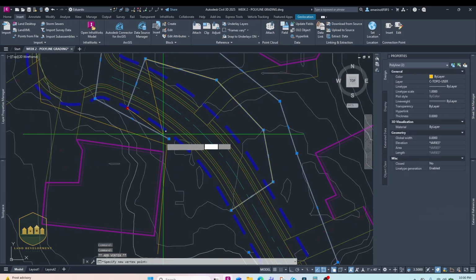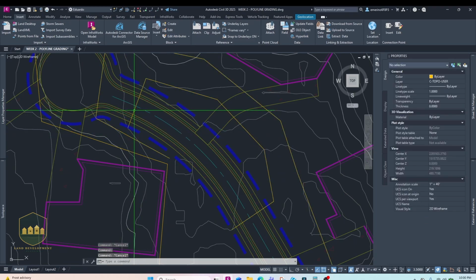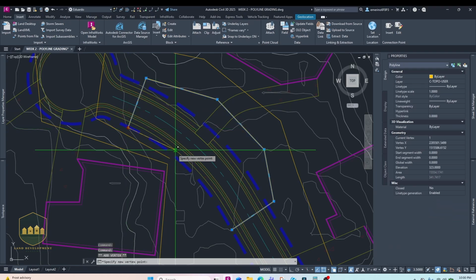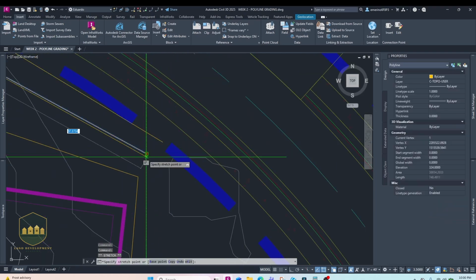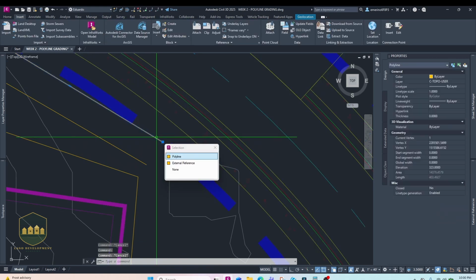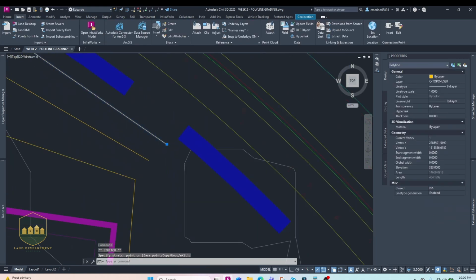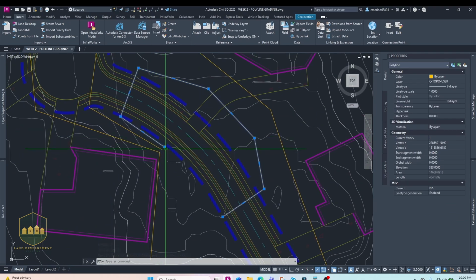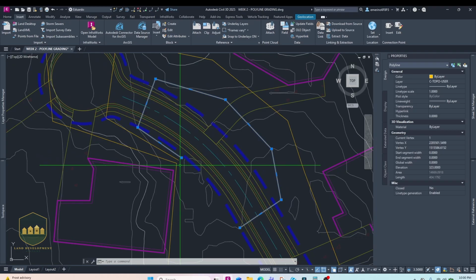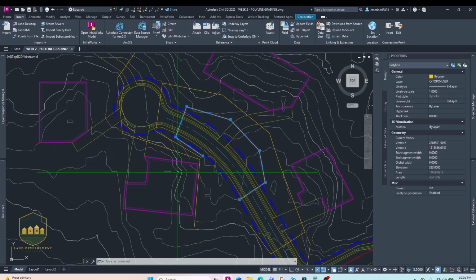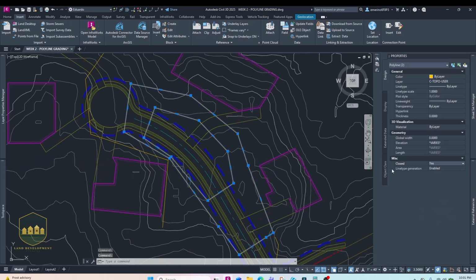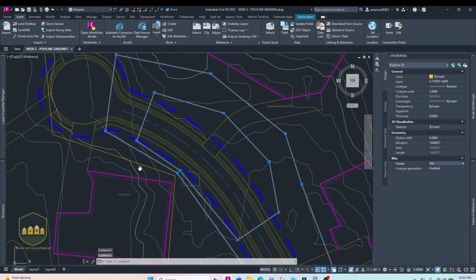Now we're getting pretty tight, which means that in this scenario, we would have to offset and make sure the lines follow at least a 2-to-1 slope. And really in this little pocket right here, I would not be comfortable with 2-to-1 slopes. Ideally, we would talk to the architect and say, look, we need to move this building this way so we can have more room here. But architects don't like listening to us, so we're just going to go ahead and try to make it work.